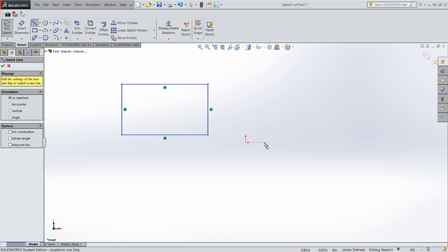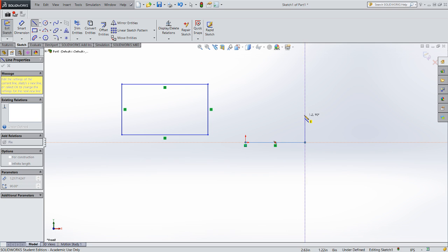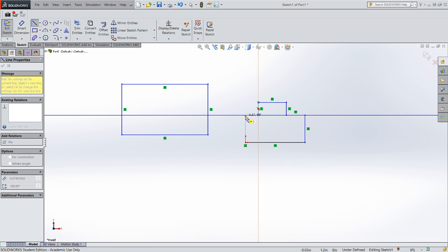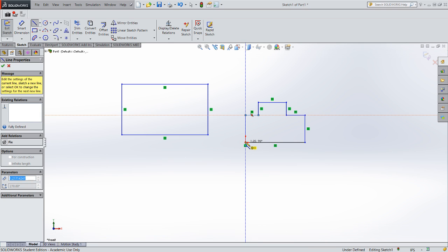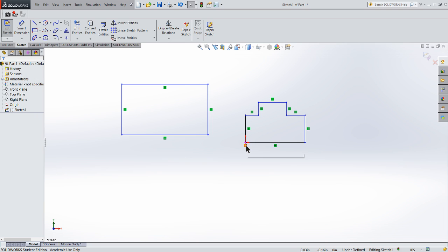So let's say that I'm going to make a box. And I'm just going to sketch a shape, a fairly simple shape. And there are several ways that I can make this same feature, but I'm just going to show you a use for geometric constraints and walk through. Right-click, select. You'll notice that we're coincident with our origin. We're horizontal, vertical, vertical, horizontal, horizontal, vertical, vertical, horizontal.